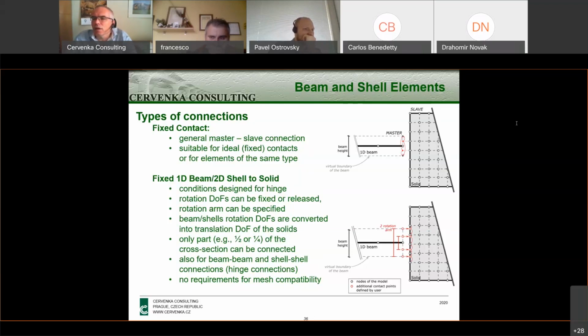Vinay is asking, is it possible to use 1D beam elements with 6 degrees of freedom at each of the two nodes for smeared rebars in place of the rebar 1D element with 1 DOF per node? So whether we can use these new beam elements as reinforcement embedded inside the concrete, like the standard truss elements in ATENA.